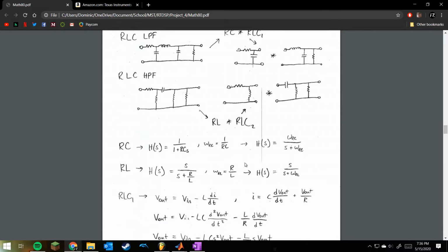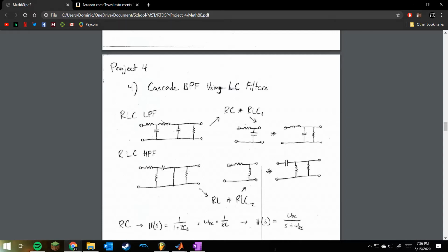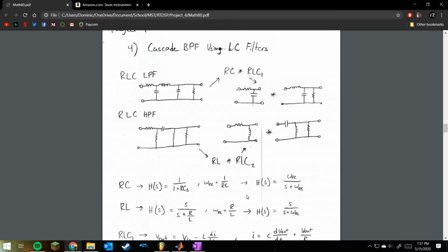And so because of that, whenever the L and C are identical, at a certain point, the reactance, yes, there it is. At some frequency, the reactances of those components match up and they cancel out, and all the current is allowed to flow, and so you see a resonant peak in your filter. So, with that said, now we will go ahead and walk through the derivation.